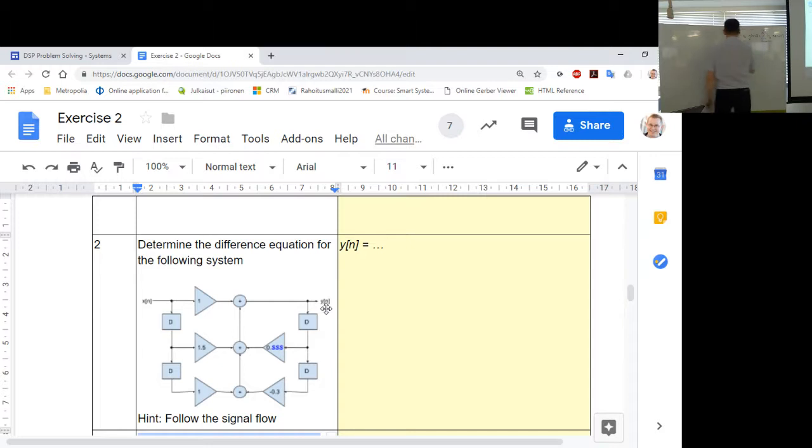So let's think that you have the difference equation, meaning how to calculate the output for the input, looks like this, minus sum of a_k times y[n-k] from 1 to N. So the second common mistake you can do here, in addition to swapping that, is to have a sign error when you move these output terms to the left-hand side of the equation.